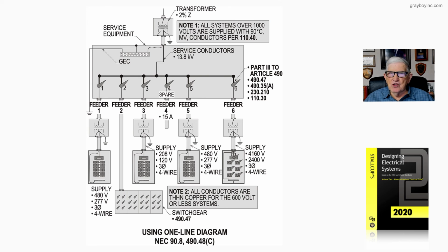What this is showing is that you can isolate locations where equipment is installed for maintenance, repair, infrared inspections, whatever you may be doing, in accordance with NFPA 70B, Chapter 7, and Annex L in NFPA 70B, if you want to review it, along with 205.2 and D.2.2 in Annex D in NFPA 70E.